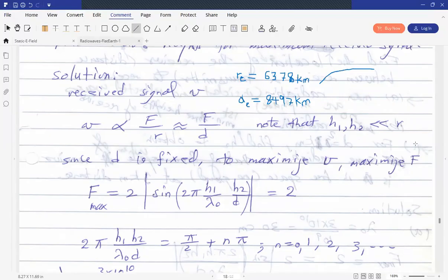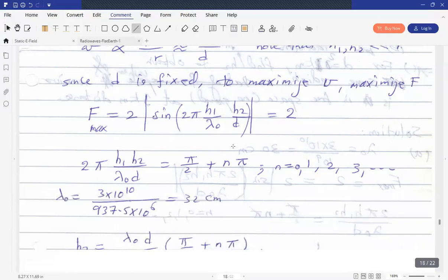Okay, so you do not use epsilon r or no. I told you that this material, this course, is an easy course. It's not difficult. It is an applied course. You use it directly in the field of engineering. So it does not have complicated equations. The equations are simple, just to understand how to apply it and to make design. So once you use the effective earth radius, you use straight rays and you do not use epsilon r, no refractive index, nothing. Okay.